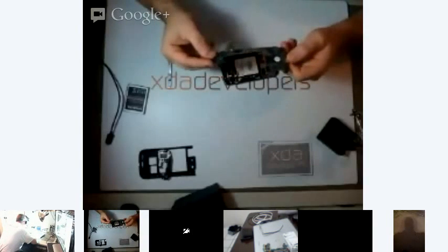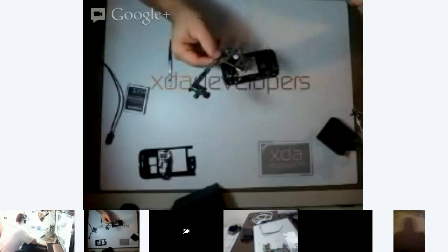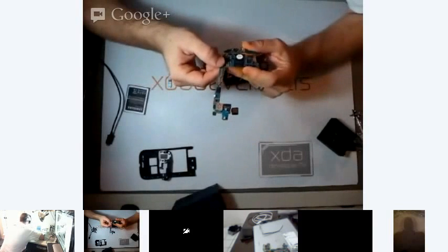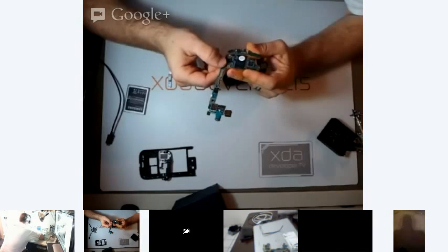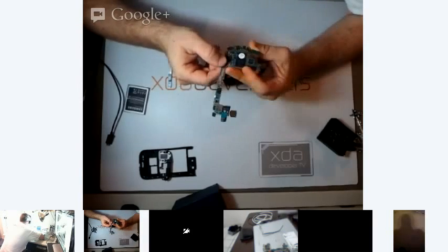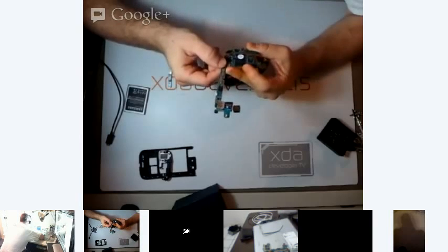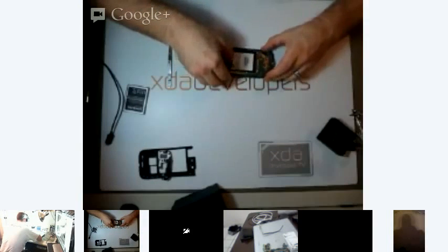Alright, so moving on a little bit. I wanted to see if I could find some sort of an eMMC disable on this device. Not that it would actually be possible to boot anything off of eMMC because the bootloaders on this device are pretty locked down, but more because I wanted to see if there were any structural things I could identify from Samsung, and it really doesn't look like there are. So let's get this thing back together, get it booting up, and start locating UART.